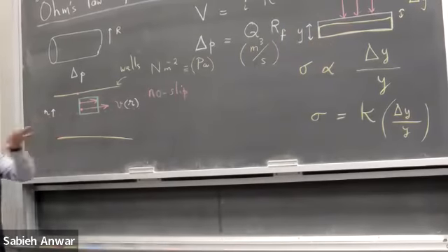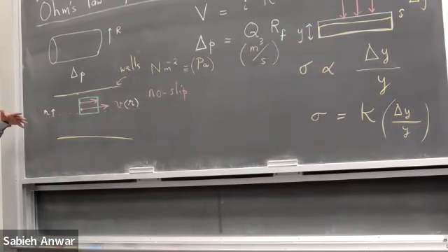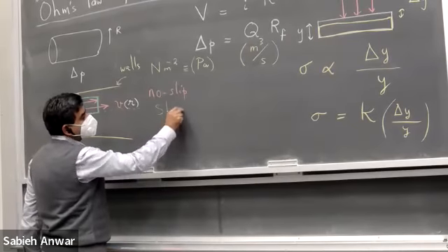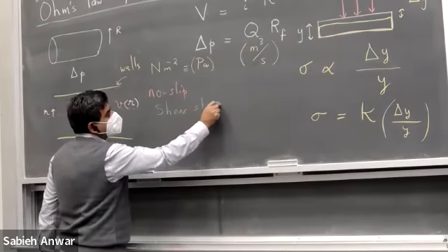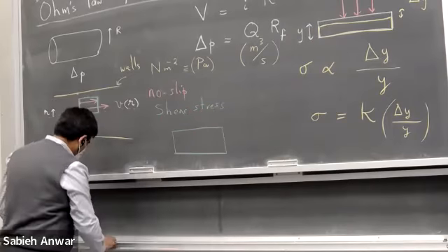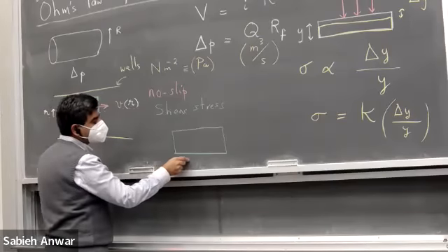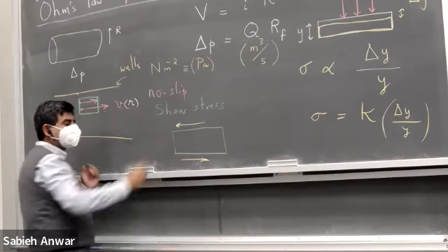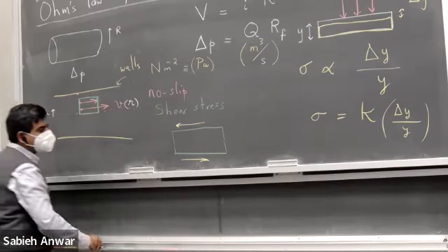In a fluid, if you were to make this object flow, you have to apply a force that is parallel to this section. In such a case, you define another kind of stress. That stress is called shear stress. So if I have a section of a solid or a fluid and I apply a force in this fashion on one surface and a force in this fashion on the other surface, then this object is going to shear.